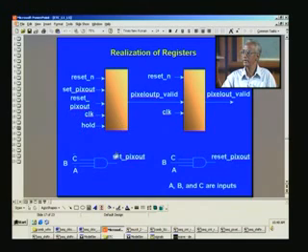And the set will happen based upon the A bar, B, C bar condition being satisfied, and when the A, B, C condition is satisfied, it will reset. This is the one reset. So this register will be reset here, and whatever is the register value here will be delayed by one clock pulse by registering in the next register, and out comes the desired value that you need.